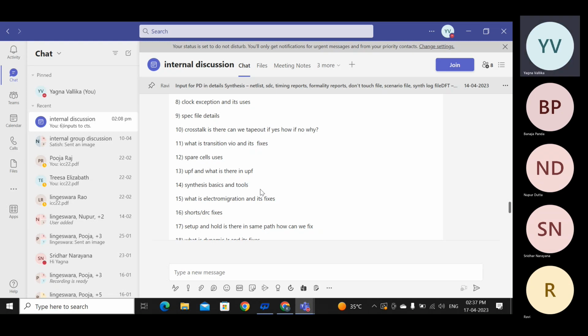Okay, let's first take the example of a library. You can open any .lib you already have. For a cell, the characterization delay table is given in the form of a matrix. On the top, the horizontal x-axis is transition, and the y-axis is cap. Let's say the farthest transition value mentioned is 0.6 nanosecond. If the transition of your cell is beyond 0.6, it will say it's violating the transition limit for that cell, because within the table it is doing interpolation.